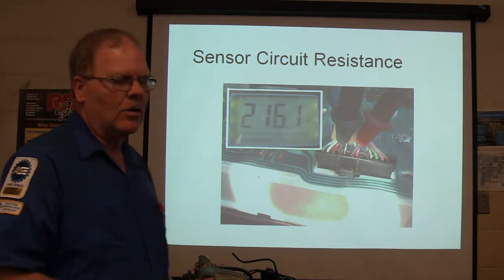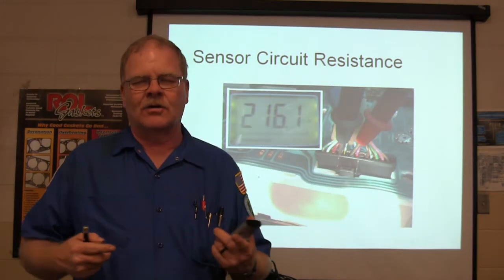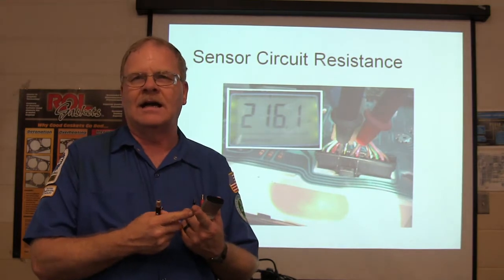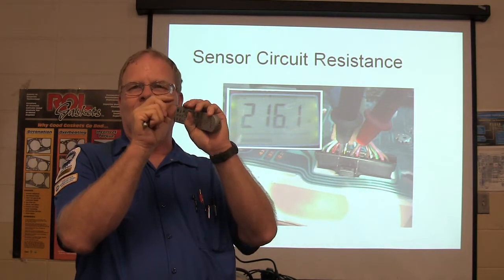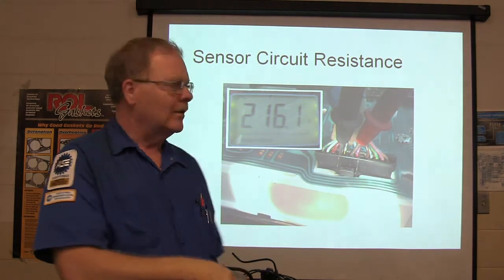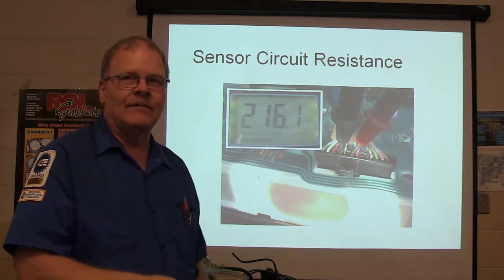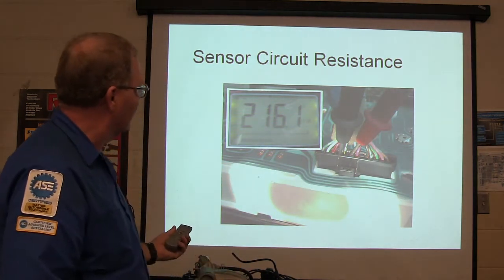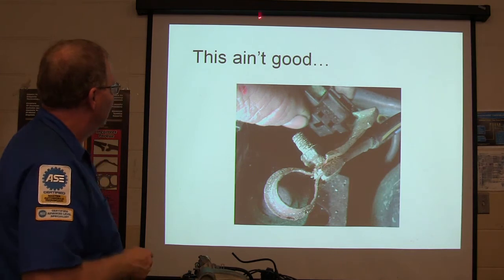Now, one of the things you don't want to do when you're doing electrical is to cram the probe in the front of that connector and destroy the connector so it can't make contact. You know what I mean? That's why I go in the back if I can, or I'll use one of those little prick tools to go in there. All right, this ain't good.